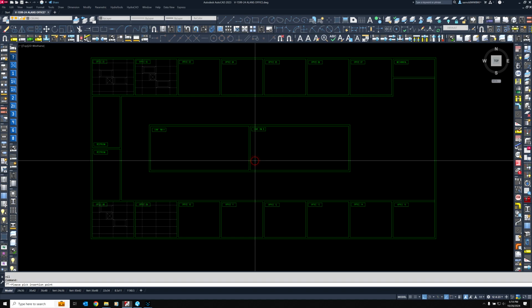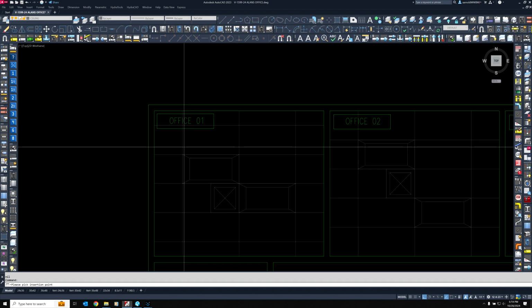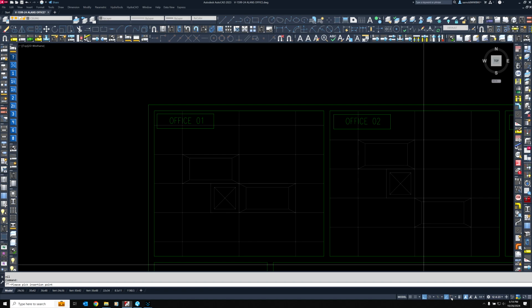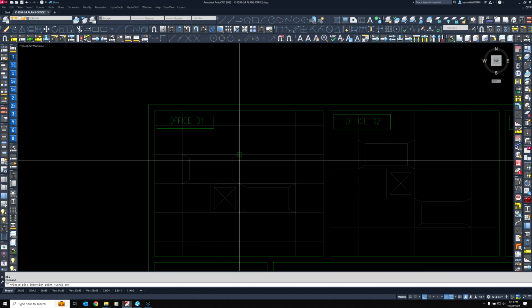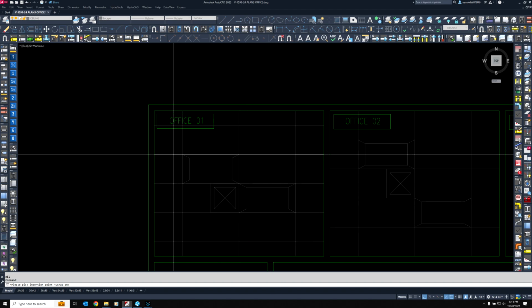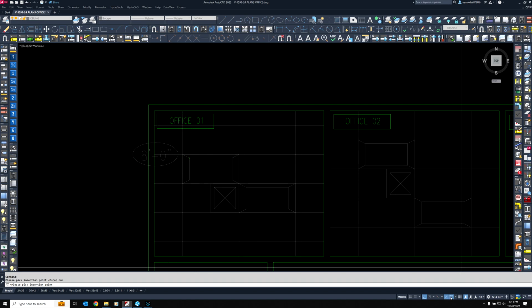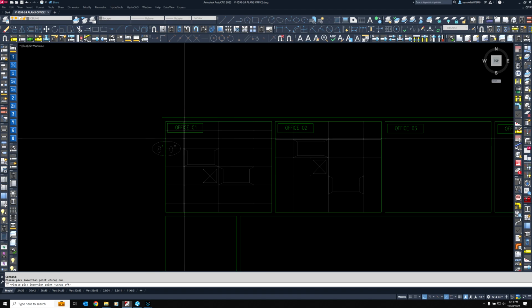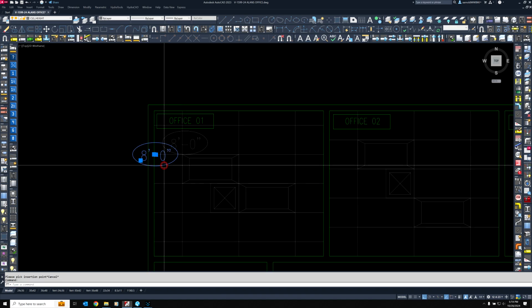You hit OK. And then again, we want to try and insert these where they're going to be out of the way of everything else. O-snaps are off. Let's just see. If my O-snaps were on, do you see what a pain in the butt that would be? It will snap to whatever end of the line you're closest to. And we don't want that to happen because then we have no control. So make sure your snaps are off. And then you can put that anywhere you want. Right there would be a much better place.